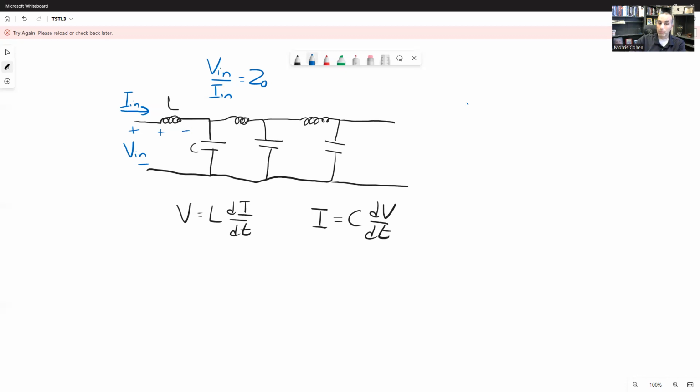The inductor, the moment you put a voltage drop on it, invariably is going to have the current start to rise, right? It's going to have a non-zero di/dt. So we start to get a little bit of current across this inductor. This current is going to start to flow because it doesn't want to go through the next inductor. It starts to flow through this capacitor. And then a capacitor, when you flow current through it, starts to charge up. It starts to build up voltage.